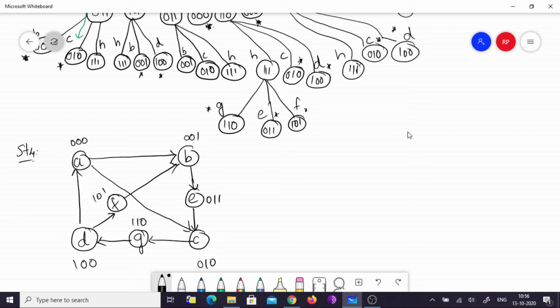So likewise, B to A is also possible, and I think we are done. If you see this new transition diagram, initially we had 4 states A, B, C, and D. Now we have introduced 3 more states so that the race condition is totally solved.